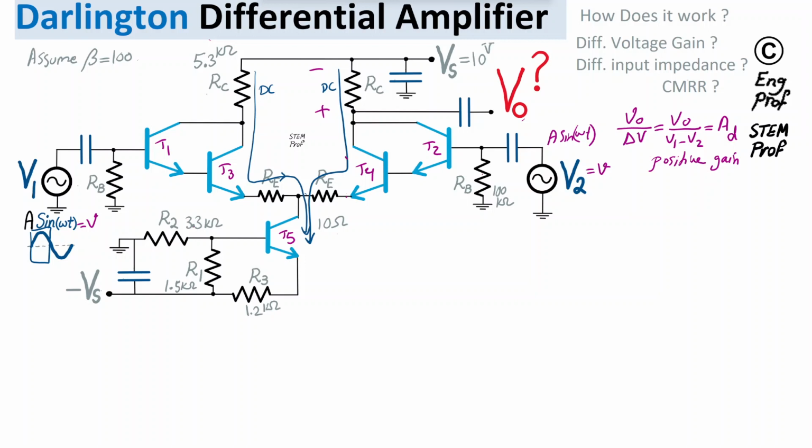So what we say is this is difference mode analysis, differential mode, and for common mode of, let's say, the differential amplifier, we want to find V out as a function of, let's say, one of the voltages, which we refer to as V1 plus V2 over 2. But since V1 and V2 are the same thing, V, basically it means V out over V.